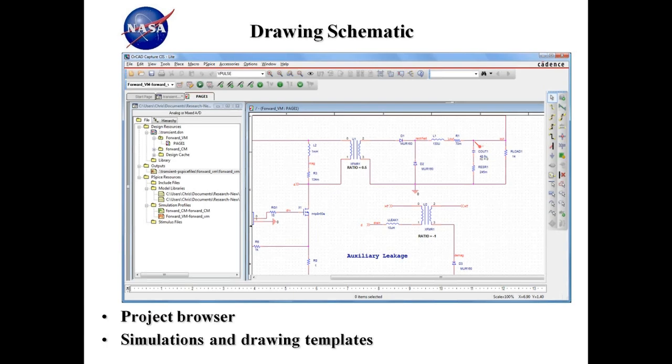On the left, you have the project browser, and the transient.dsn file there has a number of folders under it. Each one of those represents separate simulation environments. So whichever one's active is what's getting simulated, so different folders, different simulations. Moving further down, the output file, and we'll go through this, there's the netlist basically for the circuit that you have there. It won't exist until you actually click the netlist button, or if you click the actual simulate button, which takes care of netlisting for you. So that appears there. We'll look at the inside of that file in just a moment.